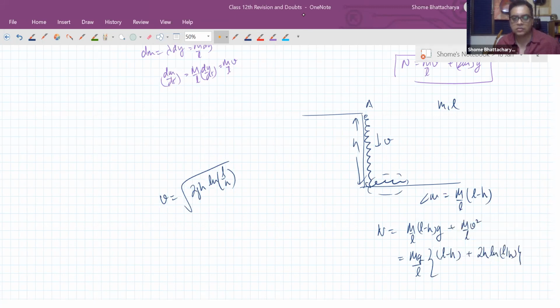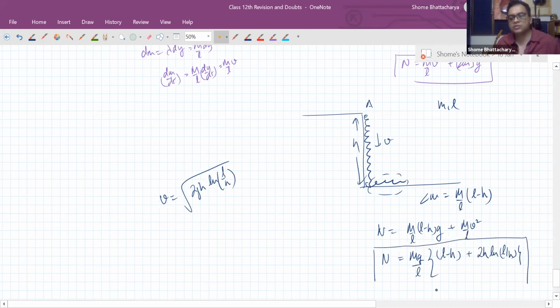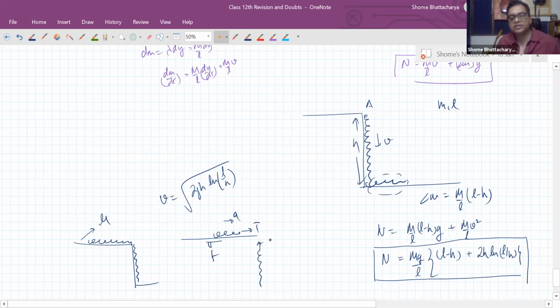Yes. Okay. So there are a couple of more versions of this question that you should know how to do. One is, you can try this yourself later. This surface has coefficient of friction mu. So then in your FBD equation for acceleration, you have to make a bit of modification. In this portion there will be friction also, and tension, and in this portion just tension and weight of that part. So you have to solve it that way. So you can try a variation of this question where there is friction also.